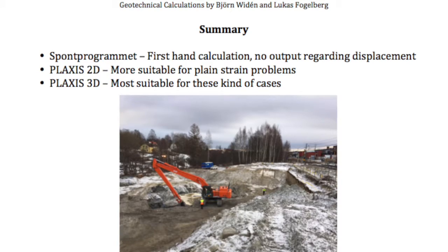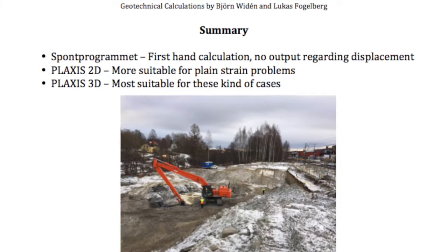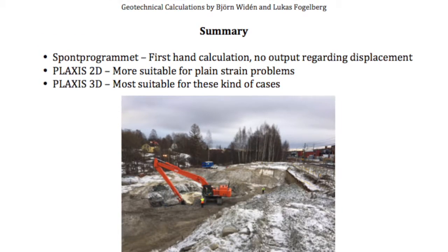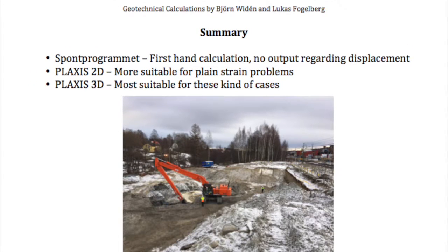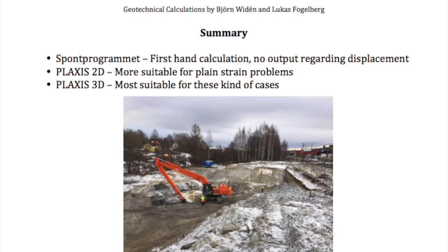For this specific case, PLAXIS 3D is most suitable since the sheet pile wall is only 40 meters long. The results can then be affected by the surrounding geometry and constructions. This is neglected in both ScreenCast and PLAXIS 2D.